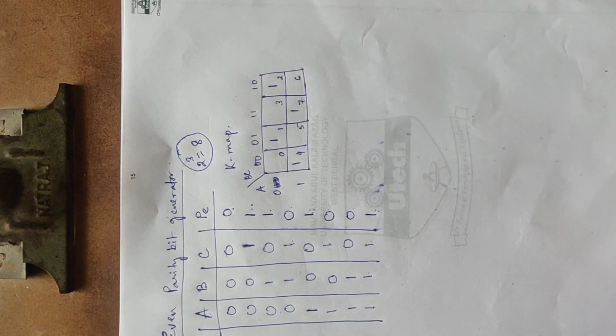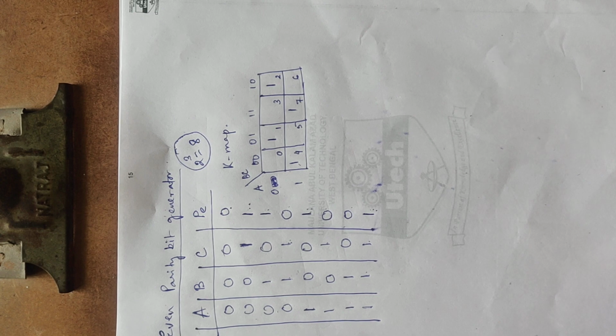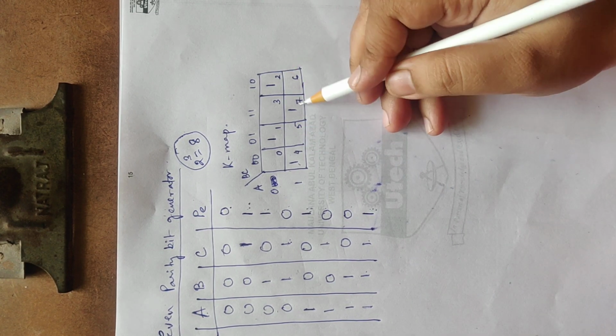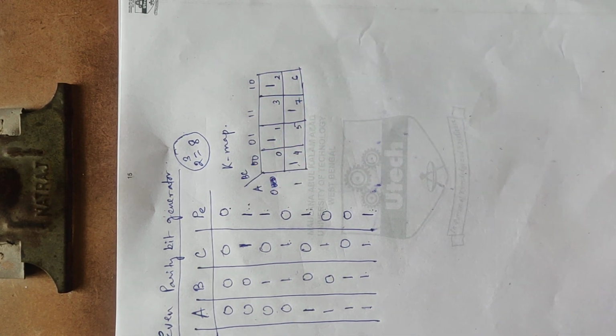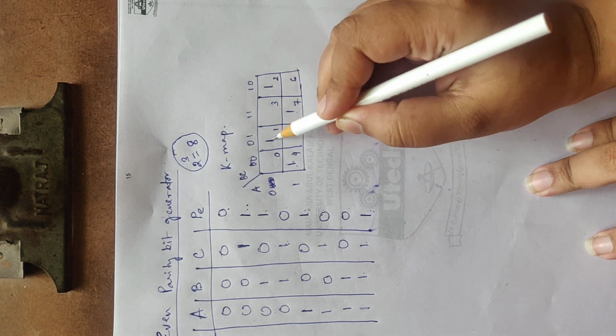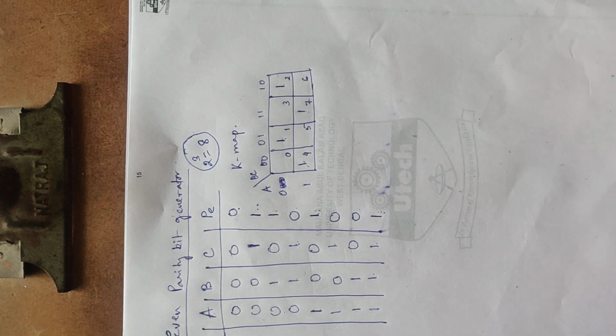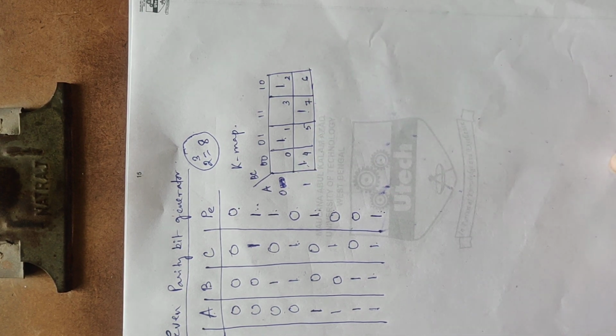Now from this we can see that with the help of the K-map it's not possible for us to simplify the Boolean expression. Moreover, all of them are present in diagonal form, which represents that normally where the ones are present in the K-map in diagonal form, naturally the Boolean expression will be in XOR form. But still, in order to experiment with that, we will write those individual expressions of the ones so that we can specify that the expression obtained after the K-map will give me an XOR.